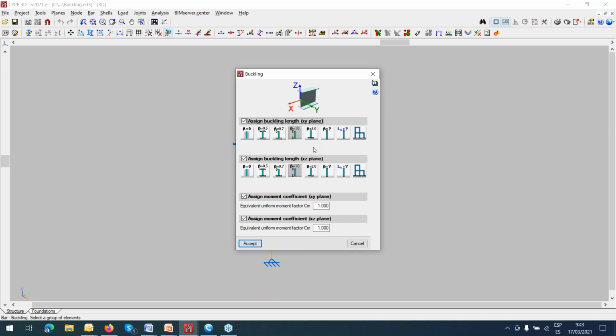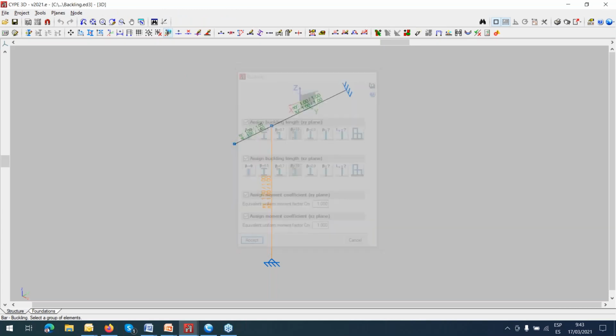Sometimes when you are working on a warehouse, one of the laterals of the warehouse is going to be supported by different elements. It could be more than one column, but in between columns you can start working with walls. The way to recreate those walls is by using the right buckling lengths. You don't need to introduce that wall in the software, but by using this information properly, you are recreating that restriction in that direction. Okay, I think this is it.